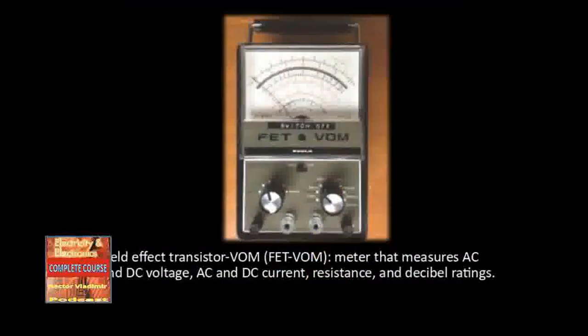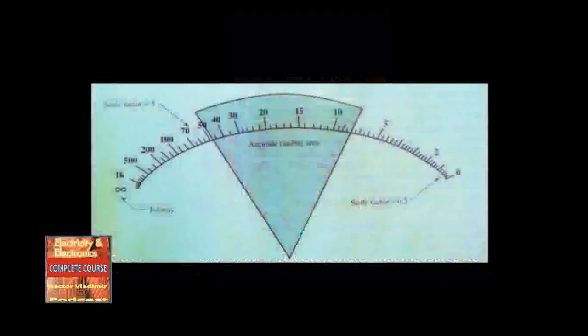Did the needle move too violently? If so, the meter range selector should be changed to a higher range. Remember, you should start on the highest range when you are not positive on the voltage or current values. The flash check will save you many dollars in meter replacement and repairs as well as wasted time. A meter has its greatest accuracy at 2/3 deflection of the meter scale. Use the range that reads as close to this deflection as possible.